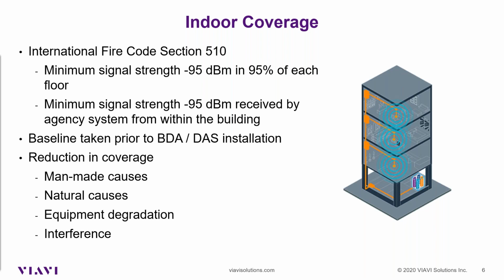Of course, band 14 goes up into our 700-800 megahertz band, up to 768 megahertz. And so if you have channels in that frequency range, and that's the downlink, of course, from the tower, so it's going to be the higher power level, that is going to have an effect on our measurements. And sometimes that can interfere with our communications as well. So interference can be a problem, and it always has been, but I think it's going to become worse as time goes on in certain areas.